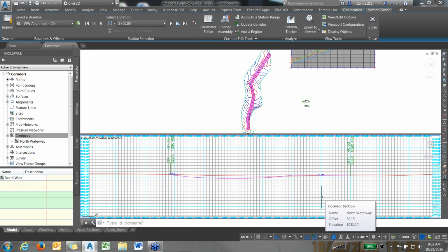So if I were to create cross-sections right now, sometimes things don't always work dynamically, and they're easy to judge. You may have to change things here and there, so this just lets us do that before we do our final set of cross-sections. But we'll do those in the next webinar. So step 4. Step 4 is creating a surface from the corridor.